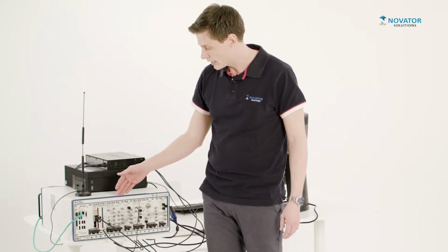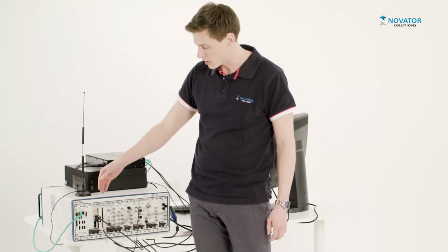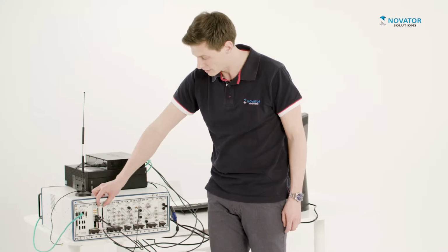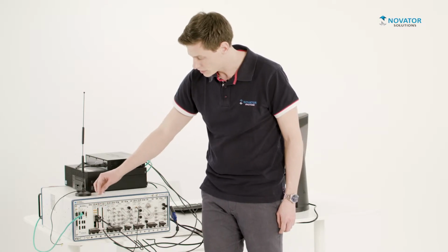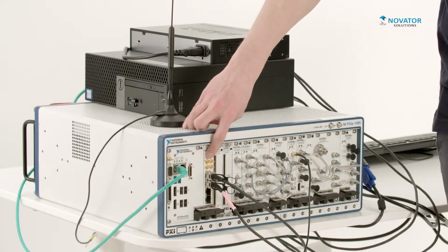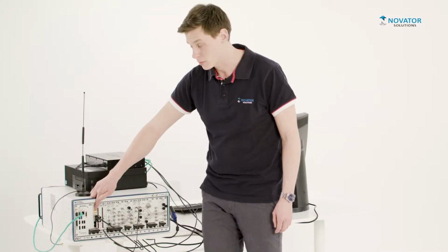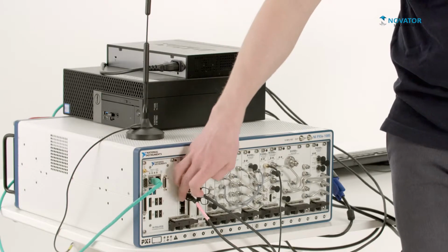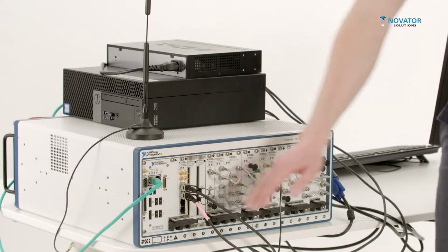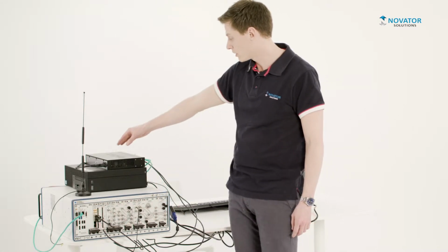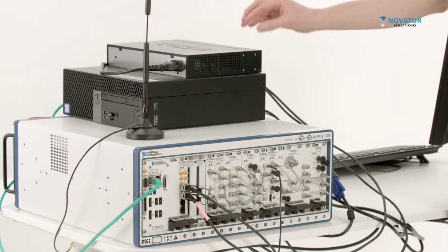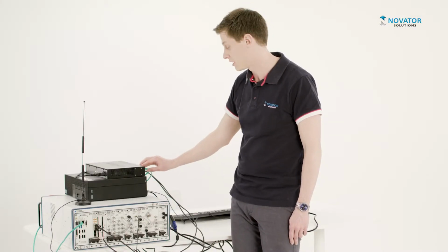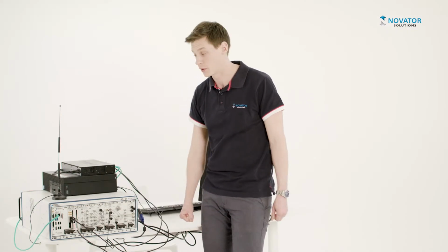These receivers will later on transmit their data over peer-to-peer to these two FPGA boards. This is where we have implemented the channelizer algorithm. After the channelization stage, we send the data to this FPGA device, which will be doing the demodulation and the filtering. After that stage, we send out the channelized data on these two 10 gigabit Ethernet SFP connections over to the switch, and then over to regular 1 gigabit Ethernet for client distribution of the channelized data. Let's go ahead and move into the software.